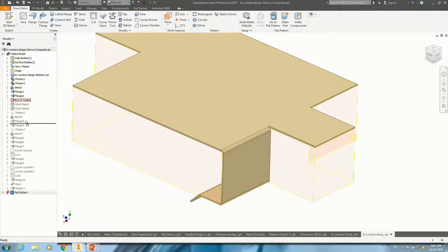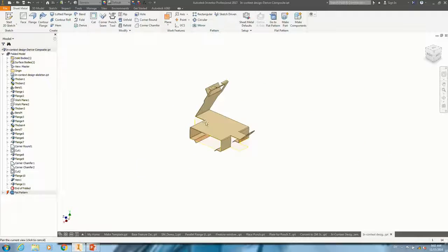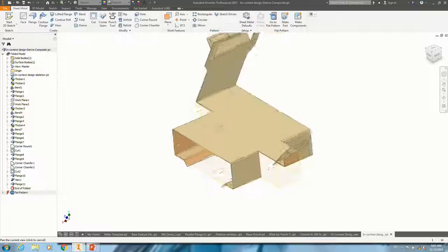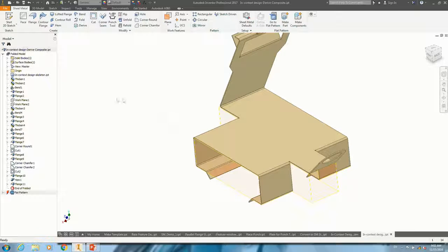The others are the same. We can just use a mirror, same as the first model, to do it. So for surface derive, the most often used tools are split, and then you use blend to connect these two bodies together.